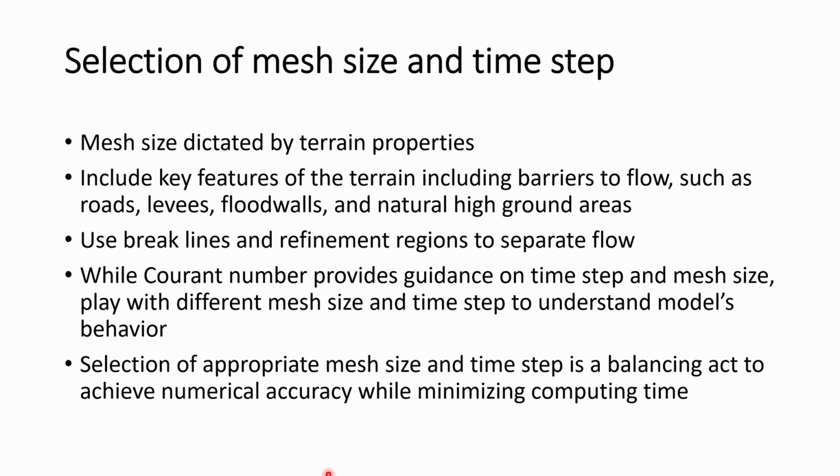Now you cannot play around a whole lot with mesh size, because that again will take time to construct your model. So many times we keep the mesh size, then we define the refinement regions, and then we play with the time step. And all this comes with more experience and more simulations you do.